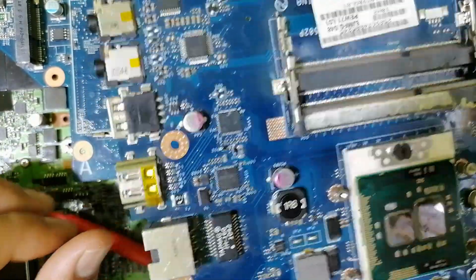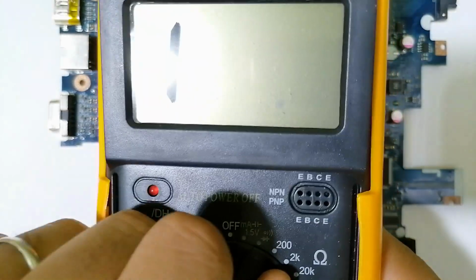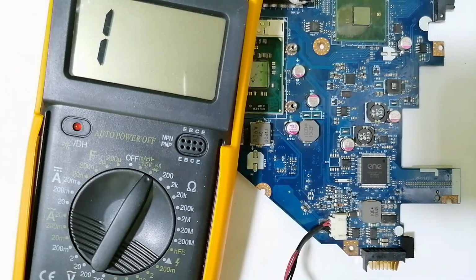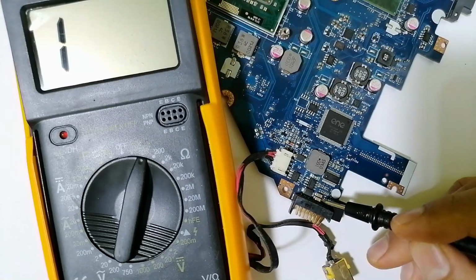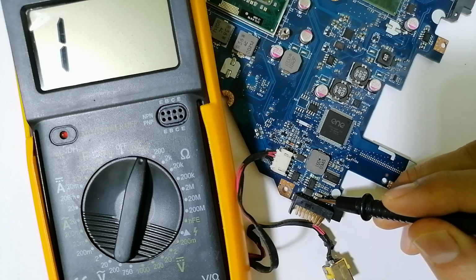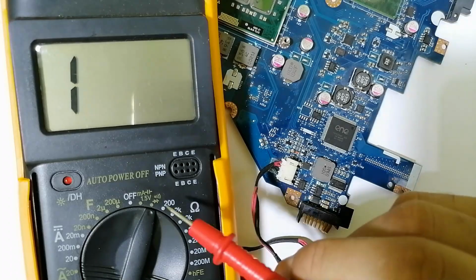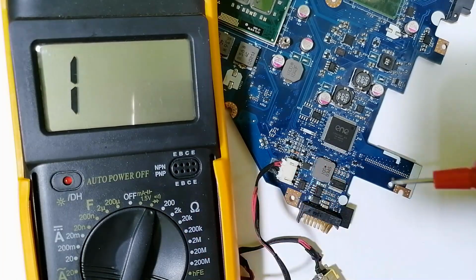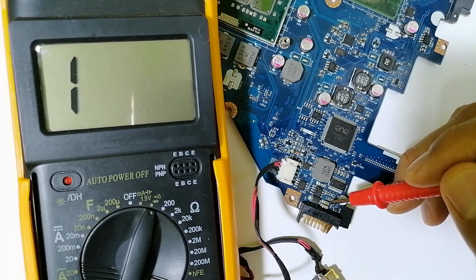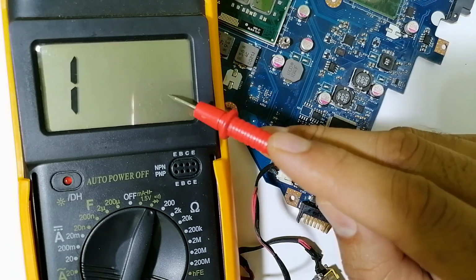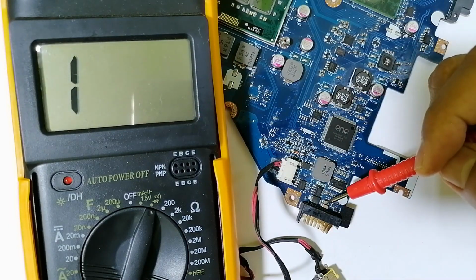So let's choose the continuity here, as you can see, and check first diodes, inductors, and ceramic capacitors, okay? Let's begin from the input here. For example, we have a ceramic capacitor. To test ceramic capacitors, it's easy. You can use the continuity option in the multimeter. If you find any buzzer or any low resistance here, it means the capacitor is shorted.